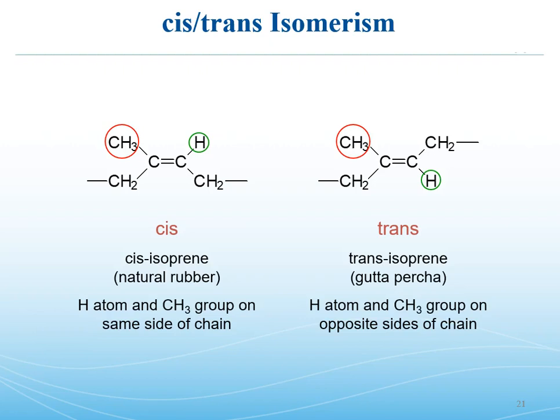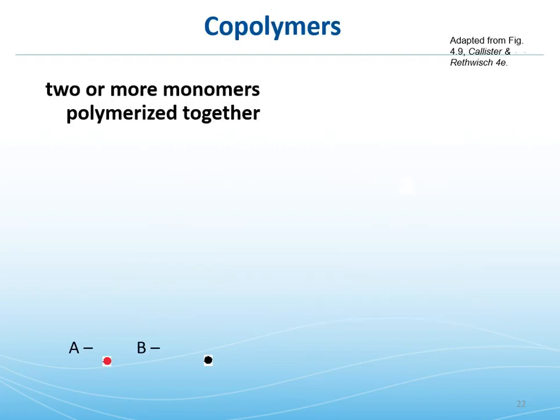So they're not mirror images, and because they're in a different position along the chain, this would have the same kind of implication as the isotactic versus syndiotactic. They'll be able to fit together a little bit differently, and so this will have implications on packing density and crystallization, which of course give rise to different mechanical properties.